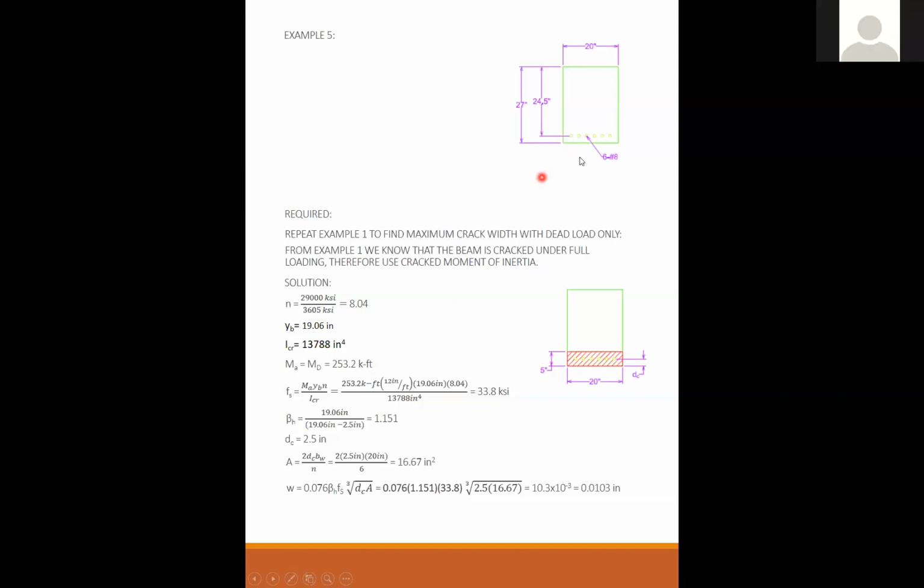Yeah. I'm assuming you can still get 6 number 8s in the 20, but, well, let's see. Just for conversation, 6 times 0.79 was 4.74. So that's 5 number 9s. If I divide by 1.27, that's 4 number 10s, 0.5356, and basically 3 number 11s.